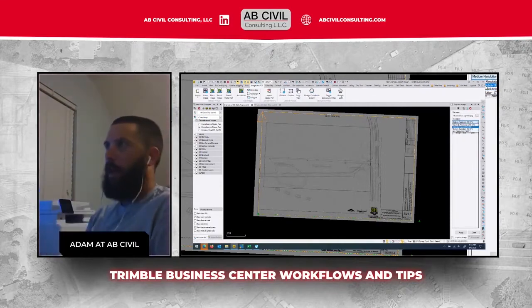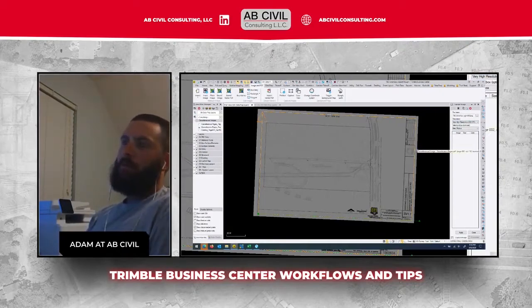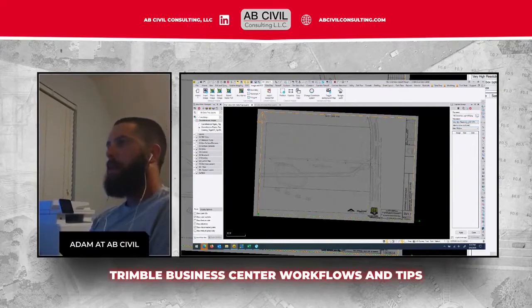Then this is important: on a job this small, with a PDF that's not a large PDF, I always do very high resolution. I do plan on toying around with vector versus raster PDFs to see if it makes a difference in the file size, because if you get a really large job with a lot of line work, the size will be too big for the data collector to handle. So very high resolution, and then this is the important step.